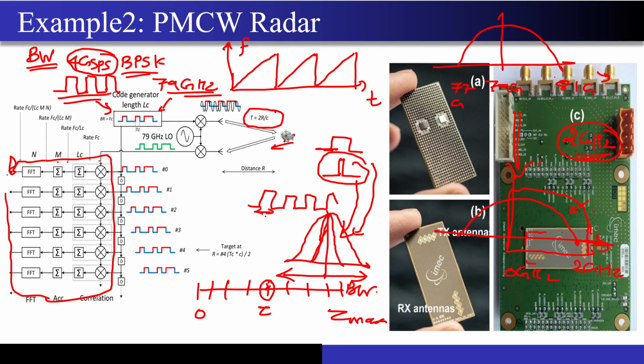If you want to design an amplifier, not only should it give me a gain of 10 or 20 dB, but at the same time its 3 dB bandwidth should be kept high enough to handle signals having a bandwidth of 2 gigahertz. Correct? Now how do you design the circuit which has a 3 dB bandwidth of maybe around 3 or 4 gigahertz, and at the same time gives you a gain of around 15 or 20 dB? This is challenging. This is not a trivial problem, right? So I just wanted to tell you that new challenges are coming up. They will pop up. Correct?